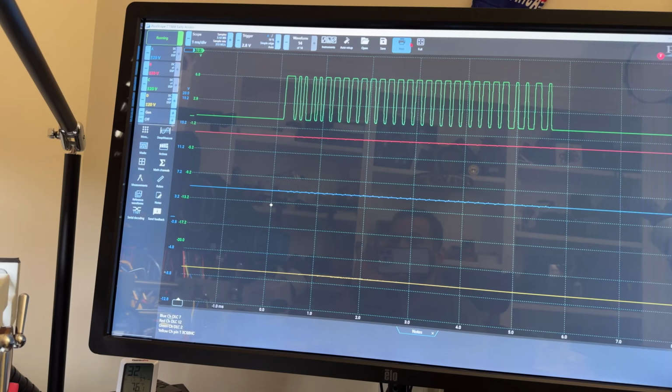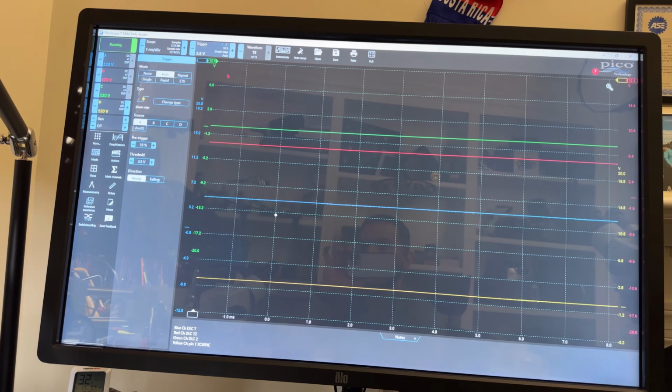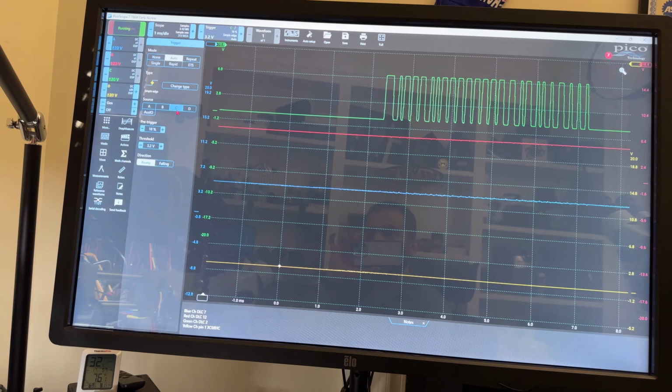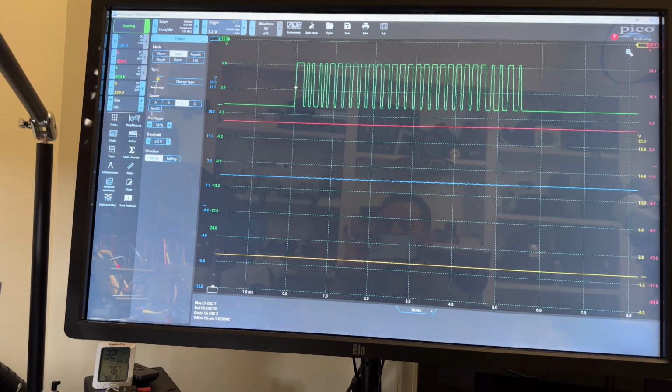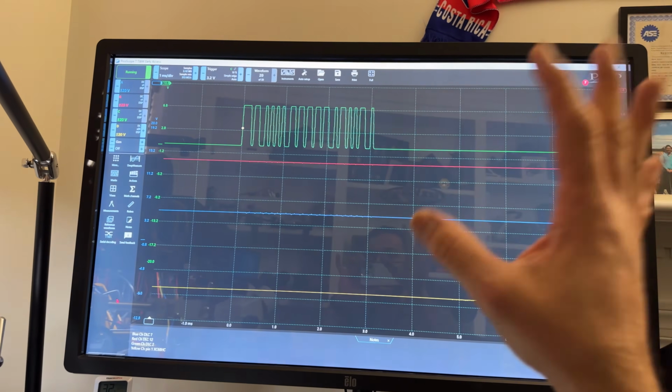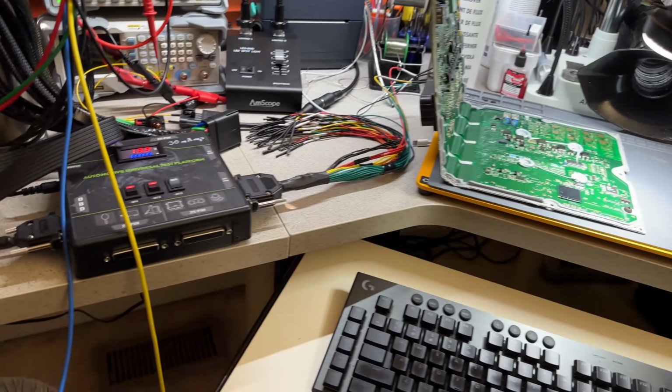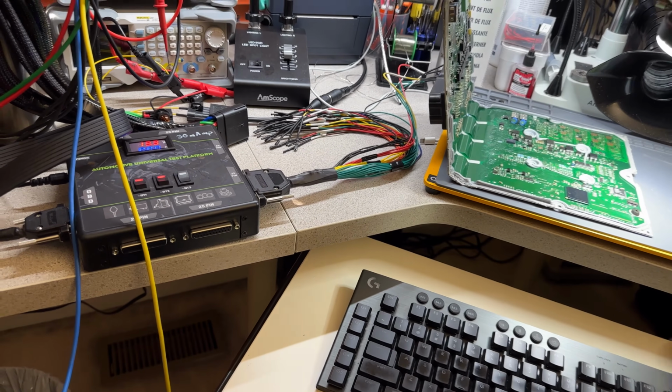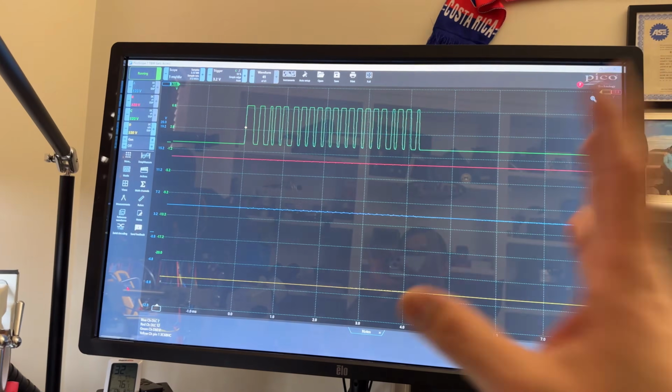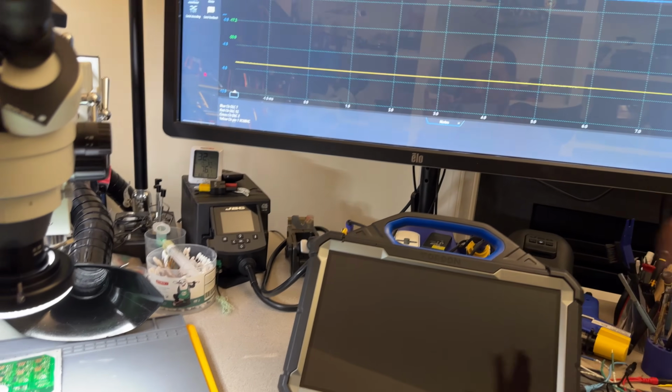You see, I got the trigger in channel A, and it's making no difference. All I will do is start the capture right there. Without a scanner talking or connected, all you will have is that on pin 2. Unless you connect the scanner, this is all you will see.